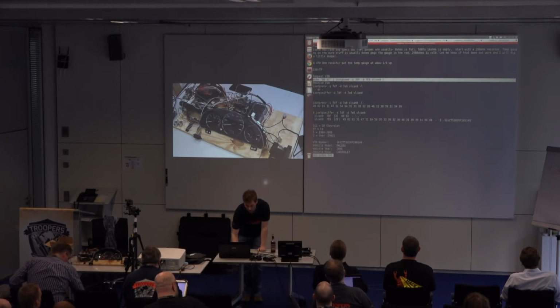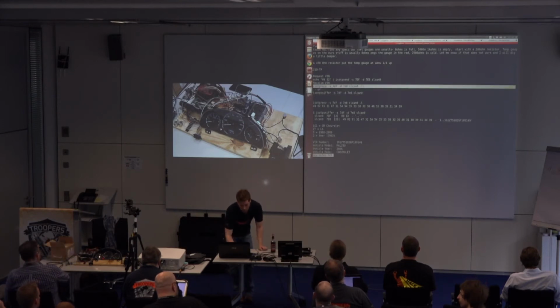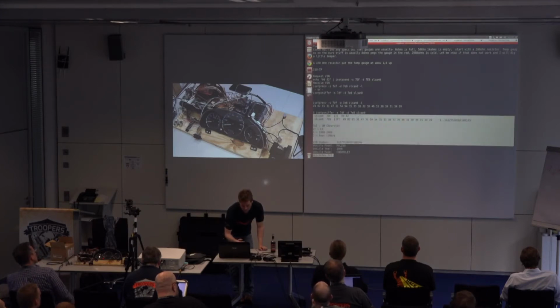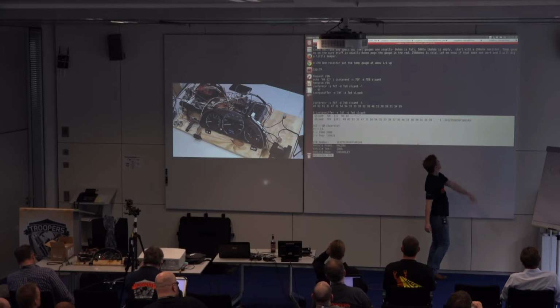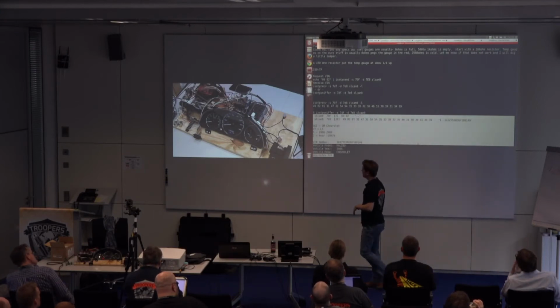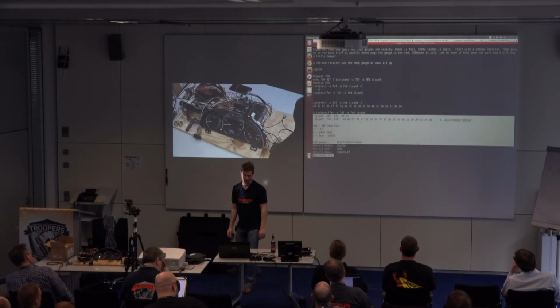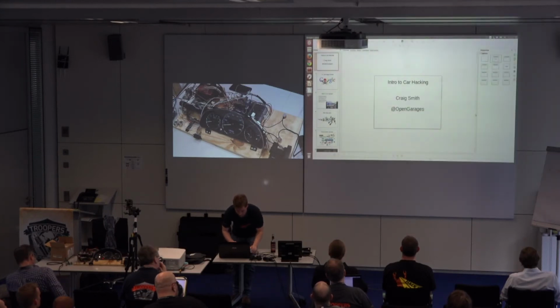And in another terminal window, you'll have a receive. It's just the same thing; it's just going to listen for a response. And so you'll get something like this. And then you can go through it. Over here is your VIN, starting at the 1. So 1G, and you can see it's more than 8 bytes. The ISO-TP will pull them all together and reassemble them for you. And then if you want, you can just punch this number into Google, and it will usually show you the rest of it. It breaks down like the 1G1 is GM Chevrolet, etc. So that's how to pull a VIN and decode it.